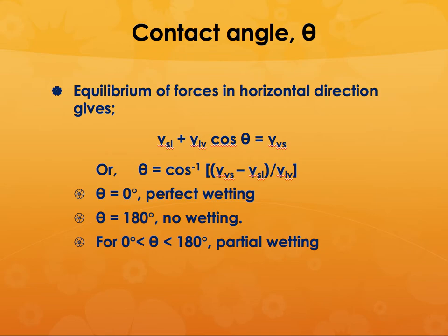So what do you know about the wetting angle and how it wets? In order for good wetting, you need to have the matrix resin spread uniformly and in a thin layer across the fiber surface. So perfect wetting is obtained when the wetting angle is equal to 0, and if it is equal to 180 degrees, then there is absolutely no wetting.